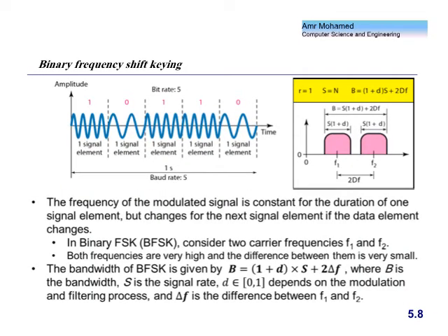Okay, so as we said, changing the amplitude is very prone to noise, particularly for a special type of noise, which is the attenuation noise, which happens all the time. Any signal that gets traveled over any type of medium loses energy, no matter what you do. So instead, I'm going to use the frequency as another alternative to send the analog signal.